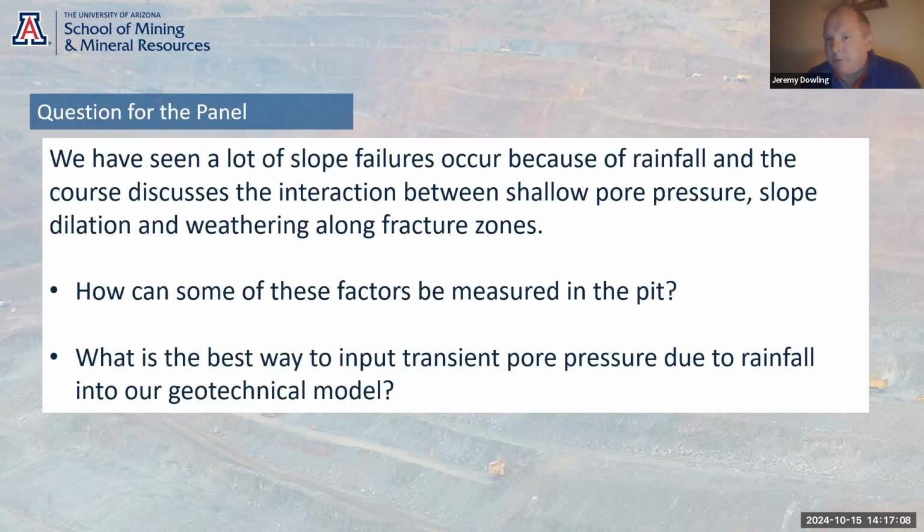And often if you plot all of that information onto the cross section with the piezometer data, you'll find that there's a lot of water present above the main piezometric surface in the pit slope. And so you can then use that information to inform the geotechnical model about where there is perched or transient water, and to get some sense of what kind of ranges of RU to try and apply.